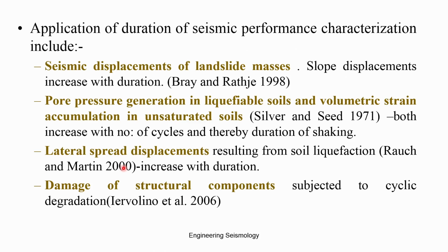The pore pressure generation for liquefaction and volumetric strain accumulation in unsaturated soil both increase with the number of cycles, and thereby the duration of the shaking. Generally, in liquefaction hazard, where the pore pressure has to be generated, the number of cycles helps to achieve the pore pressure very fast and to a very high level. So, in those kinds of places, the duration of the shaking is very important.